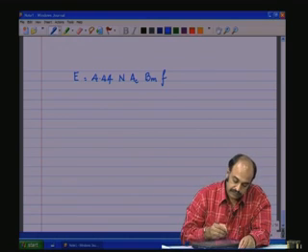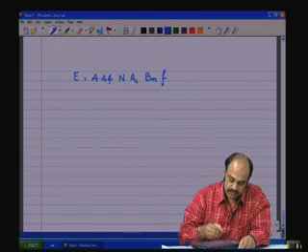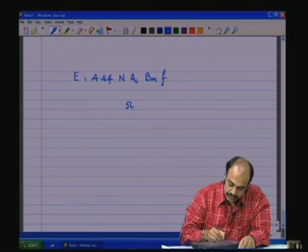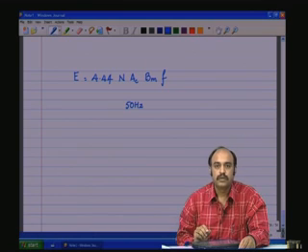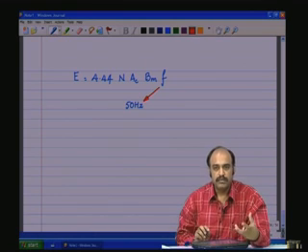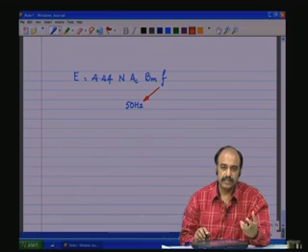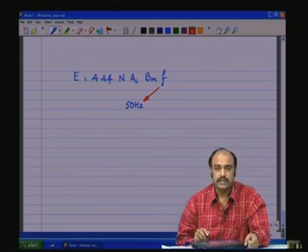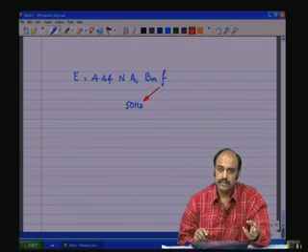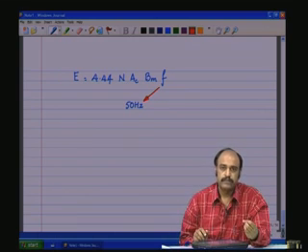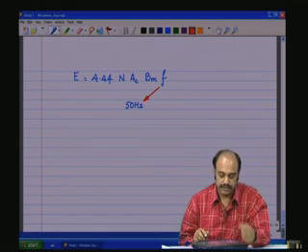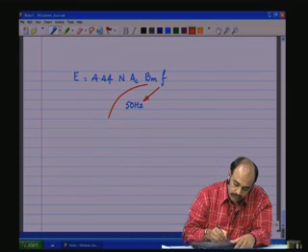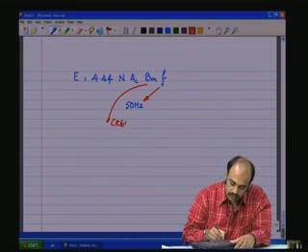Now, here for our mains, which is 50 hertz, the most common types of core materials in the market, especially for the 50 hertz frequency, are the CRGO, which is the cold rolled grain oriented, or the CRNGO, the cold rolled non grain oriented, which is slightly less expensive. So, if we are using, let us say CRGO, this would be around 1 Tesla as the design value.